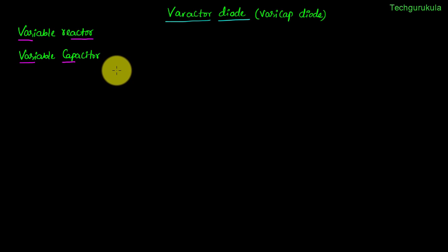A conventional PN junction diode has a capacitance property which changes with respect to the potential applied across the PN junction diode. But a Varactor diode is specially designed to exploit the voltage variable property of the junction capacitance. When we say junction capacitance, it's actually the transition capacitance of the PN junction. Usually a Varactor diode would be one side highly doped and on the other side the doping would be specifically tailored and modified to meet the application requirement.